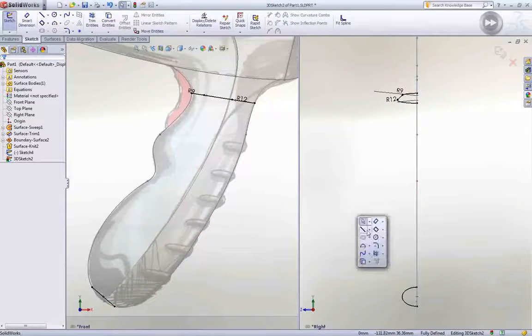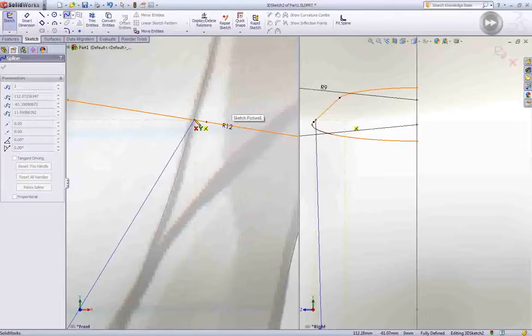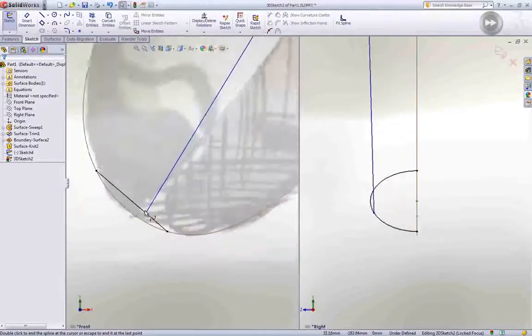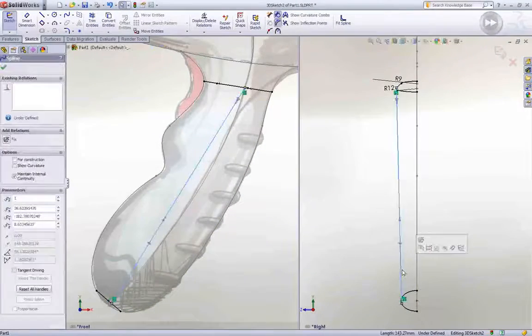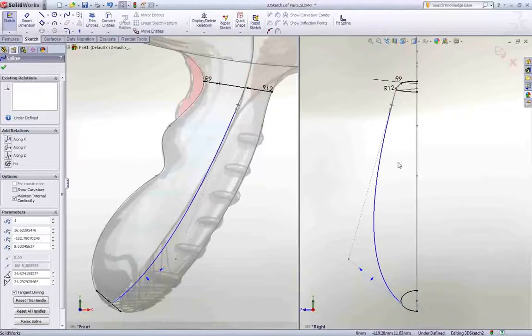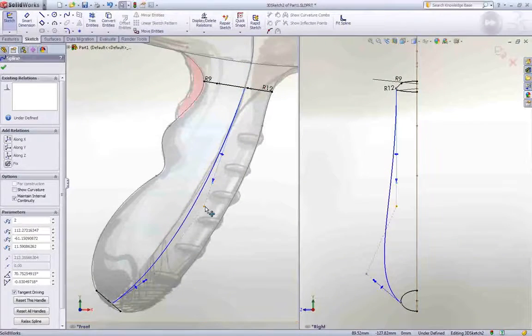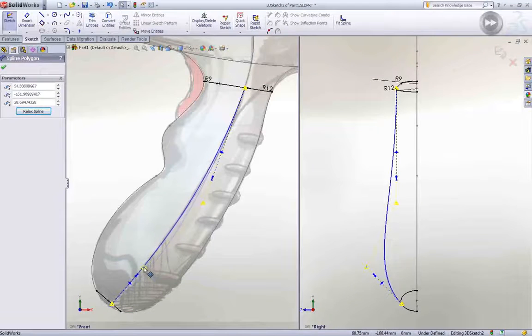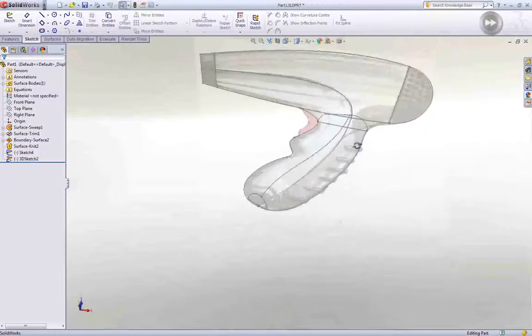3D curves are often created by projecting two planar profiles, but this is not always possible or easy to visualize. Splitting the screen into two or more viewports and linking them makes it easy to sketch complex geometry. To fine-tune your splines, you need tangency handles and control polygons, and must be able to adjust them in each view at the same time. Curvature continuity to existing curves and surfaces is also of vital importance.